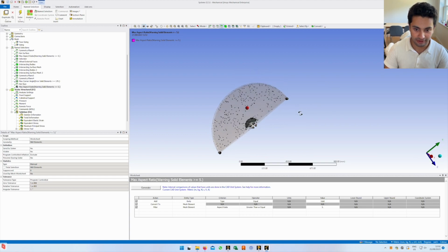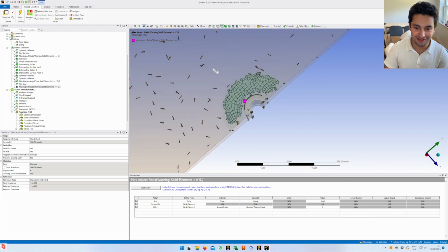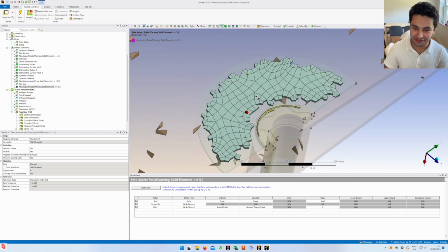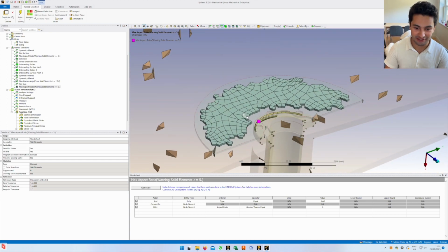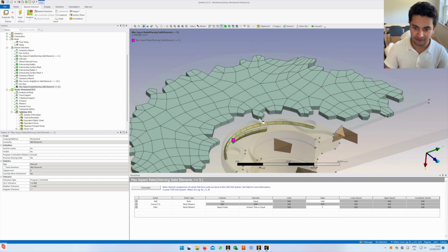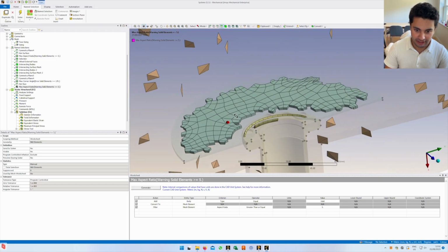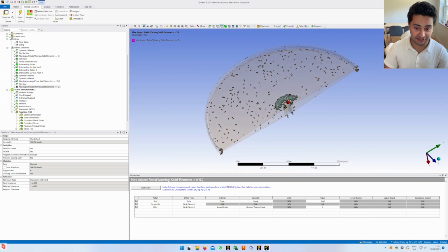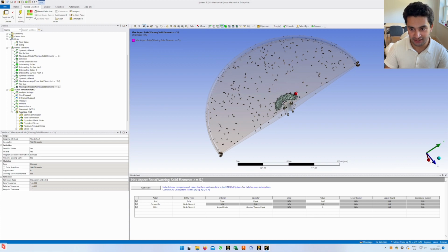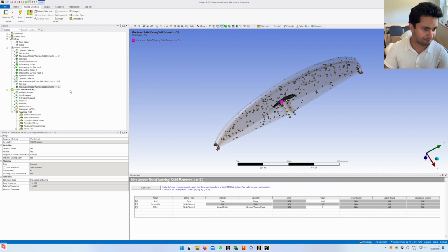aspect ratio warnings. And we'll see most of them are actually in the brake disc, which is perhaps the most simple bit of the model. So this would be quite easy to solve. The most significant loads are applied elsewhere, so I might okay this, but this just gives you an idea of how to find the elements of your model that might need adjusting.